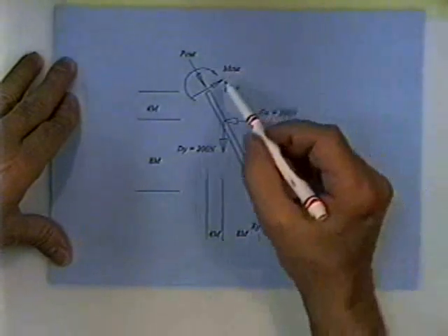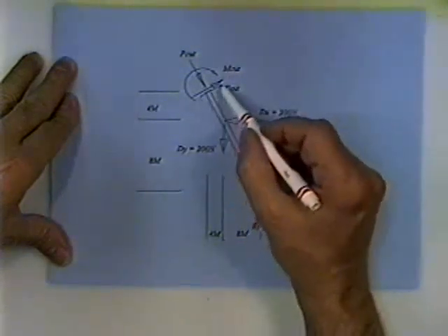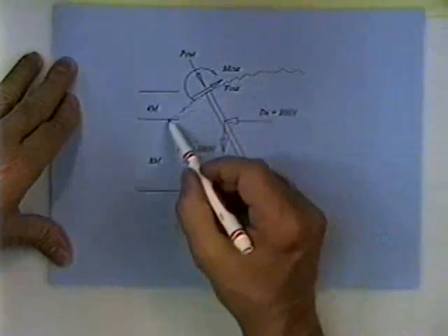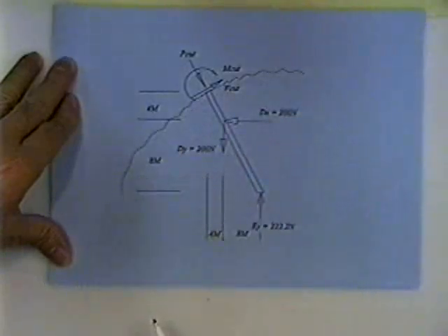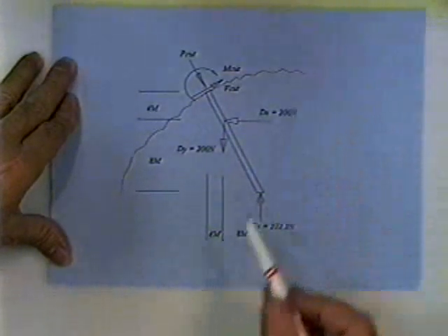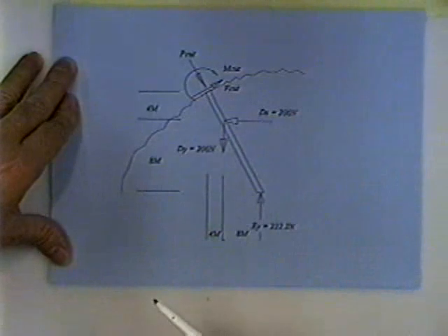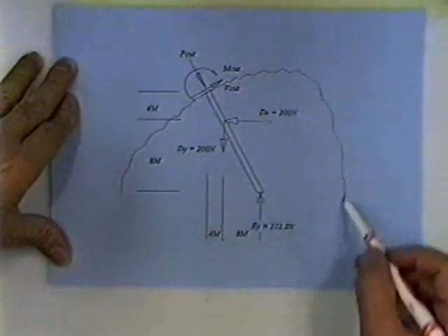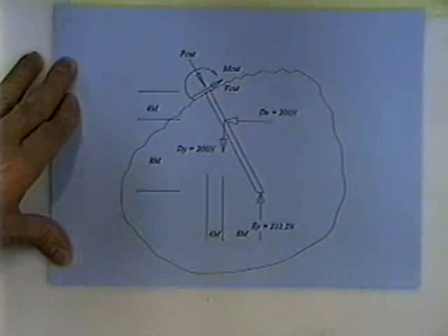Someone asked me to solve for the forces inside of the member, 4 meters above point D. So what I did is to expose the forces inside the member at that point. I cut the member and isolated the bottom half of it. I could just as easily have cut the top half out. In fact, probably would have been better because there would have been fewer forces acting on the structure. But either way works nicely.